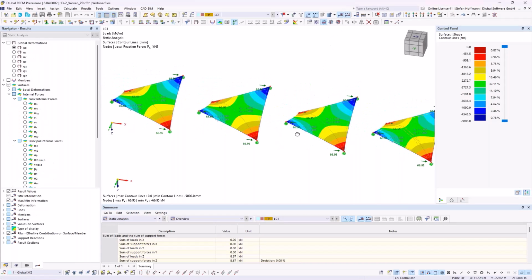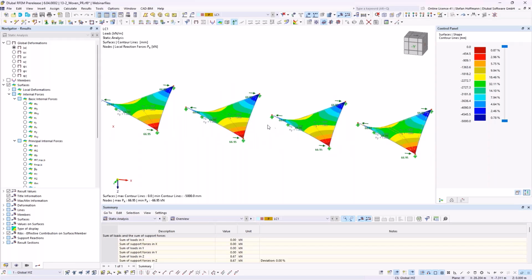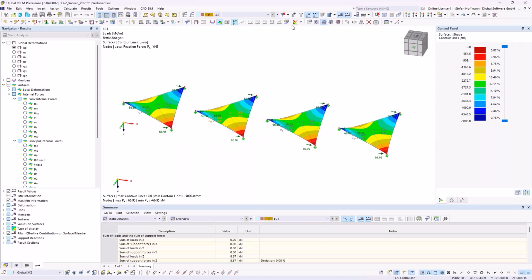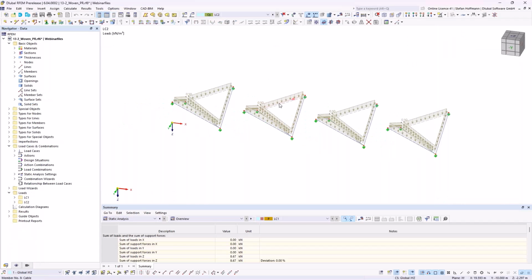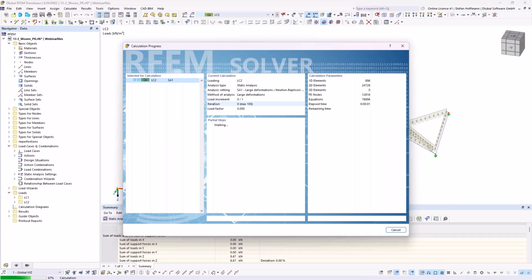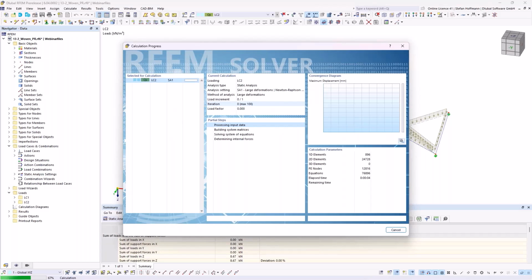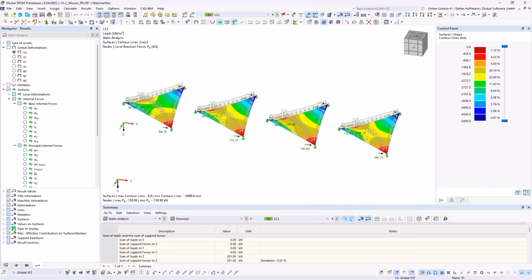But still, as told, we receive the same results for our form finding process because the boundary conditions are the same. And due to the fact that we define the prestress, we will receive in this state the same shape. If we now apply a load to our form found structure, all the material properties and also the boundary conditions, etc. will matter. So even if you now would have the same members, the stiffness of the system will now be given a bit more attention than it is in the form finding process. Also, the prestress will maybe redistribute if you use some form finding supports. I will show you soon how they are used.